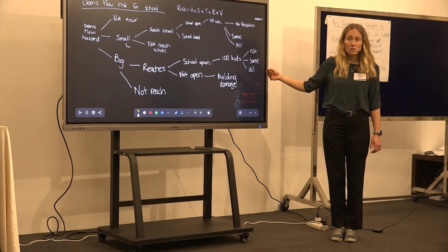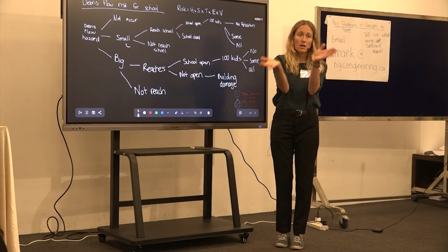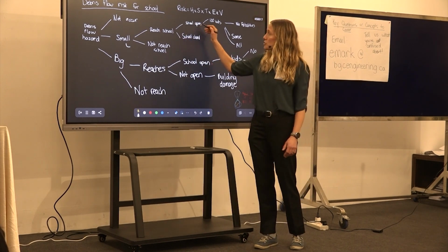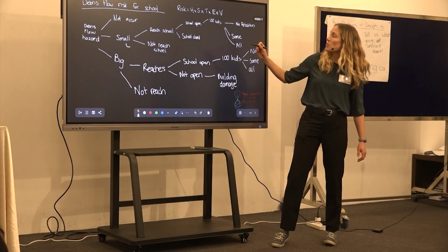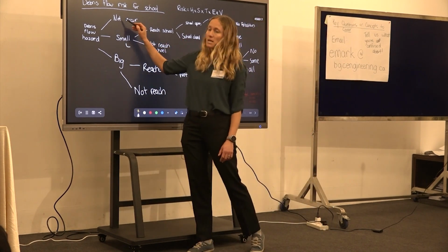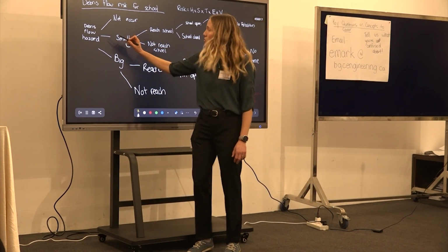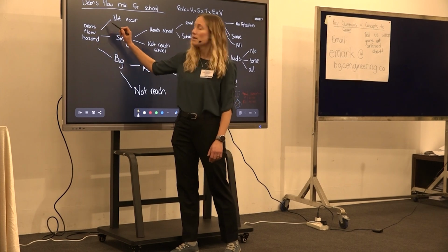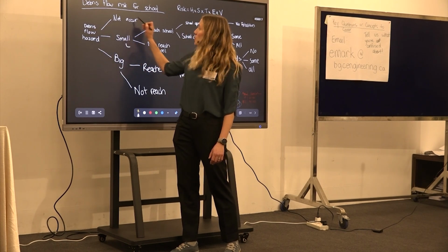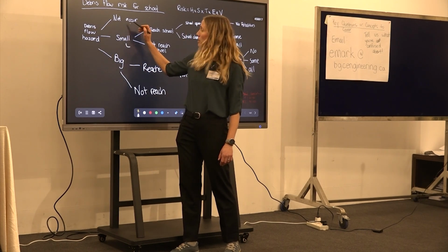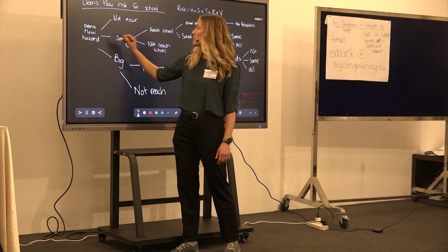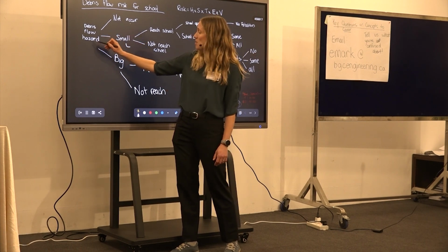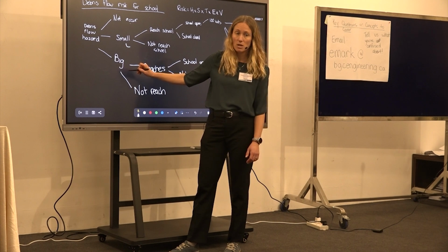So now what we need to do a quantitative risk assessment is to calculate the risk for each of those pathways. To do that, there's a few rules that we need to follow. One of the rules is that at every branch of the tree, you're going to assign a probability. There's a probability in each year that the debris flow hazard doesn't occur. There's a probability that a small one occurs, a probability that a big one occurs.